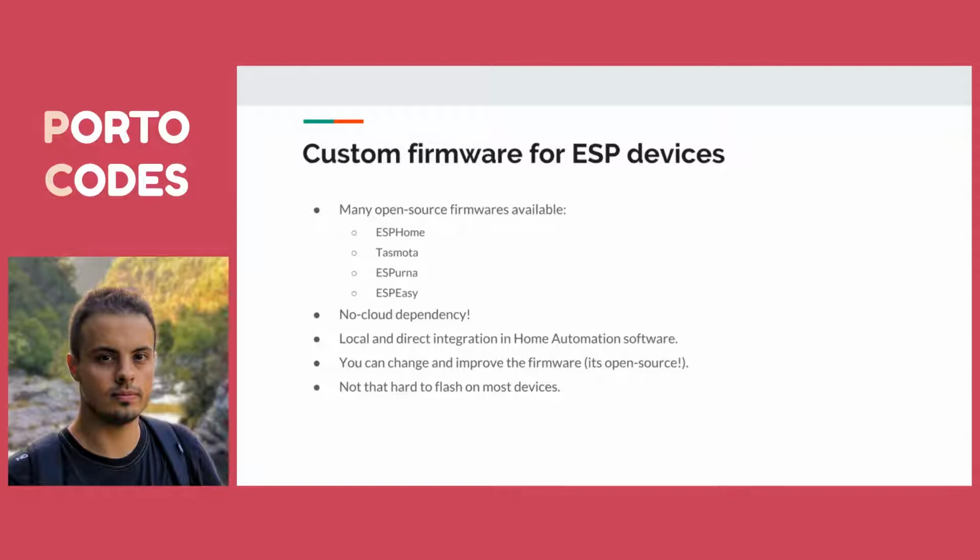And yeah, you just need to flash it. It's not that hard to flash on most of those devices. You can find a lot of tutorials online. Even if you don't have soldering skills, you don't need them for most of them. So you just buy the programmer. Yeah, it's a USB to serial converter. You connect the cables there, hold it with your finger for a second if you don't want to solder them, and it's flashed. You close it, you connect it to power, and yeah, never flash it with the power connected to a power outlet. It will not be very safe.